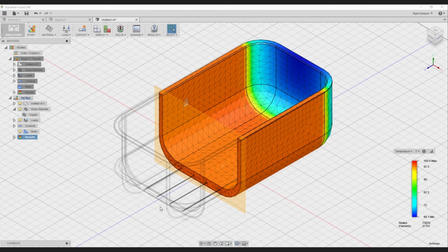We applied 100 degrees to the heating element here, and if you look, this whole thing is almost in the high 90s or 100. And why is this? You look at this and you can't believe all of the sims that you do. In this case, there is a problem. If everything here was 97 degrees, you'd definitely run into some issues. So you can't believe everything you get out of the program. You have to make sure all of this is right. That's the reasoning why your setup is really important.